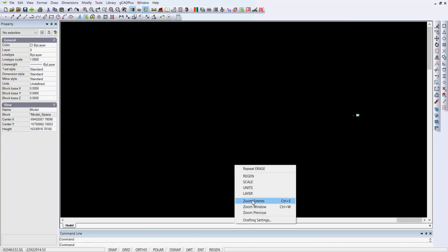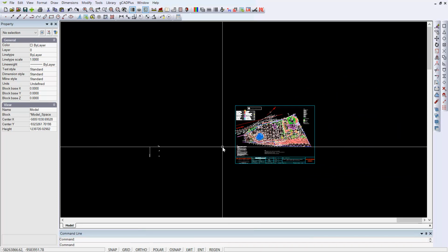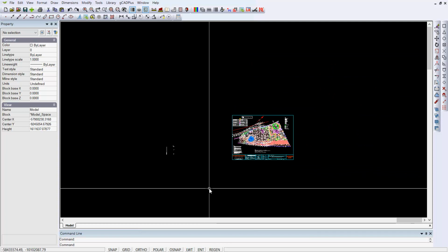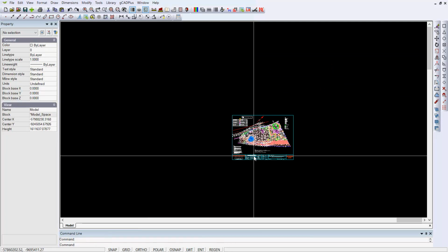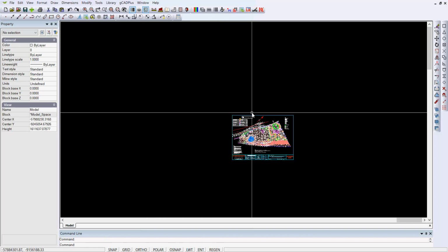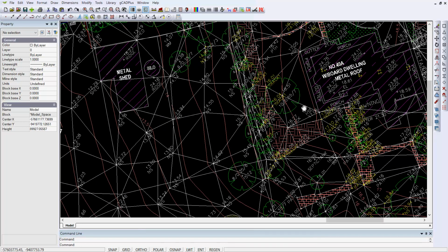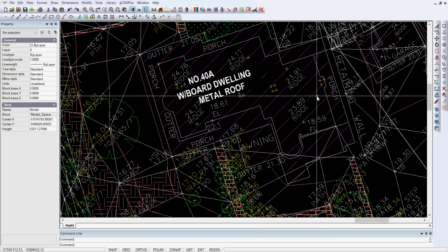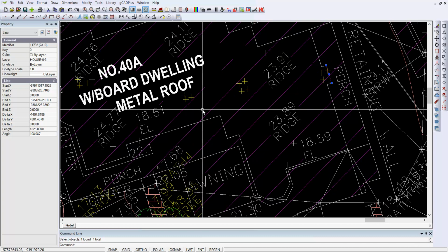So it's way, way away from our site, so I'd be confident about erasing it. And we'll just try zoom extents again, regen the drawing, zoom extents again, and you can see we're getting closer, but there's still some, I don't want to be insulting, but rubbish in there. So now we've got what we want, and I'll zoom in on that area in the front of the building, and we'll just select that line, that porch line again, and there we are, 4525.